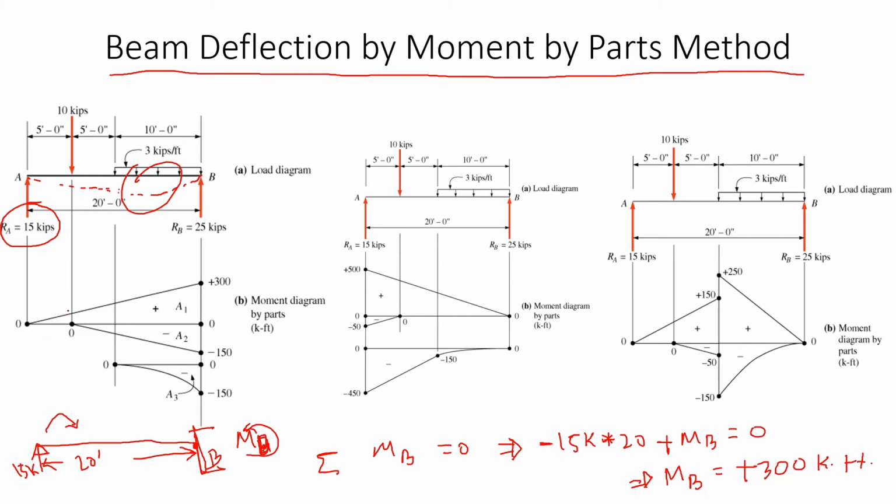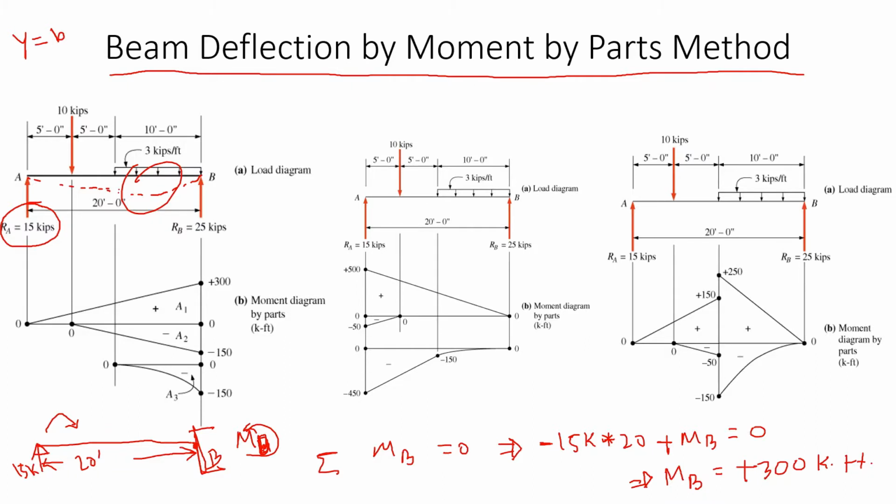and because it's a concentrated load, the moment equation is of the y equals mx plus c type. The load equation is a constant, so y equals constant b. Or we can say simply load P equals constant, or b, and then the moment is 1 degree more, because moment is load times distance. So it's a first degree equation like this, a triangle.